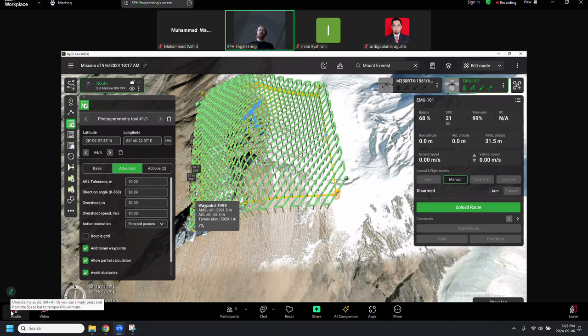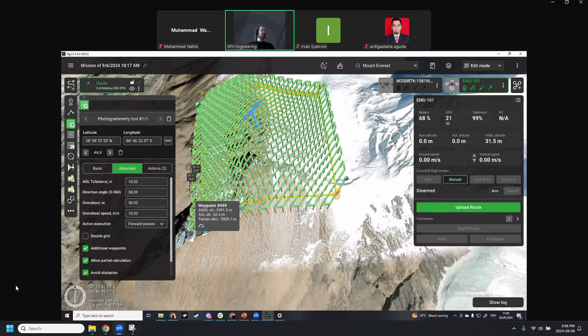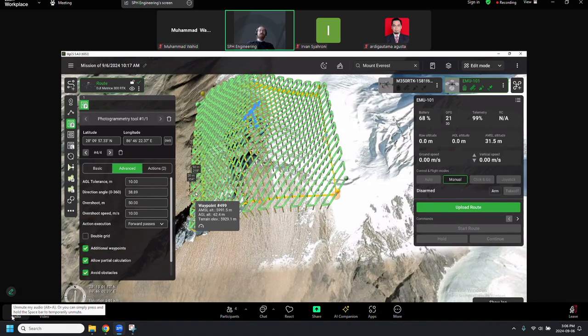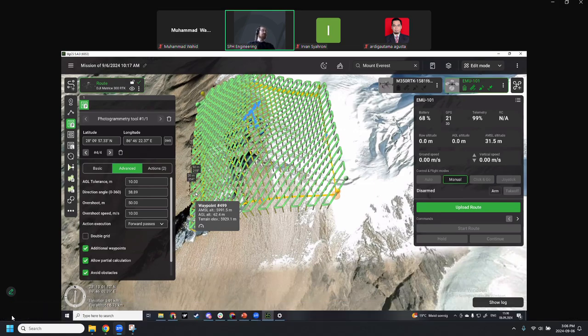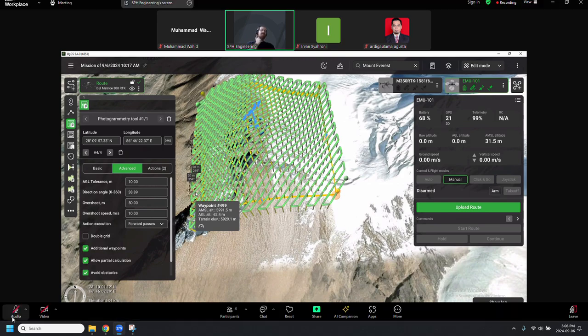Well, in a perfect world, we would just use a radar or laser altimeter on the drone, and then with the rangefinder altitude mode, the altitude will always be constant. So the AGL tolerance parameter isn't even used at that point.